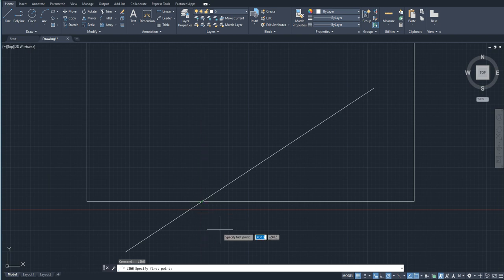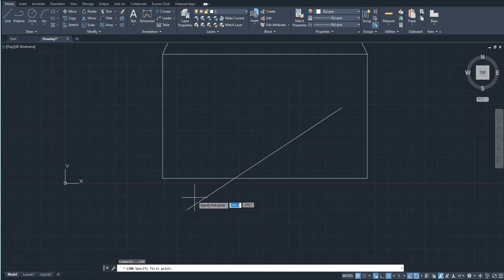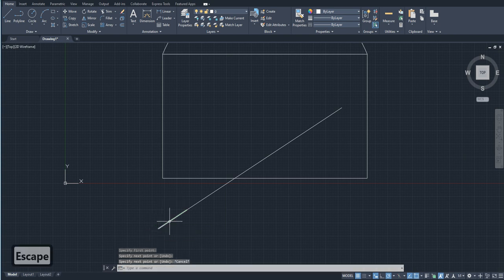The next is extension. Suppose I want to make an extension of this line. It's a bit tricky. I just click on the end point and you see I can't make an extension over here. But if I just hover over this line and then I extend my line over here, I can make an extension of this line. It's written extension 676 slash 212 degrees. So that's what it is. That's the extension, people.